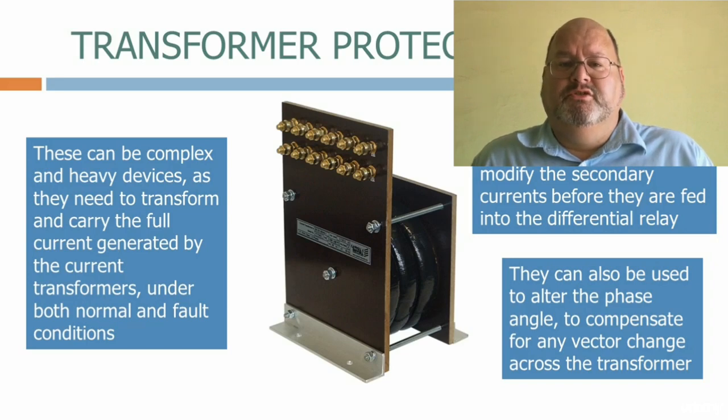The unit principle can be used on a transformer, but we need to take into account the fact that the current vectors have been changed by the transformer, both in their magnitude due to the transformer turns ratio and also in angle by the phase difference created by the transformer vector group. This does add some complexity to the scheme, but does not add too much additional delay.